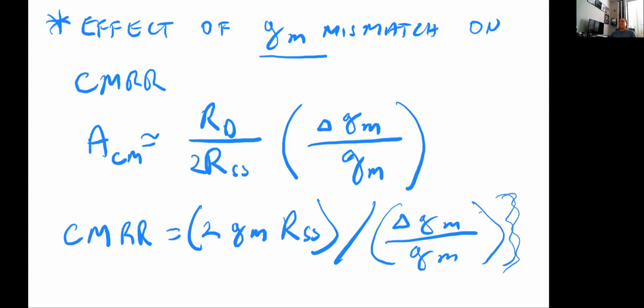Now, as we keep building this op-amp, we know that the op-amp has two inputs, and they're going into this input differential pair. After that, we're going to have gain stages, and later on, we'll put together the whole thing. But those gain stages are single-ended. They are not differential. So we are going to have a way, a mode or a method to convert that differential output that the differential input pair gives us to what is called a single-ended signal.